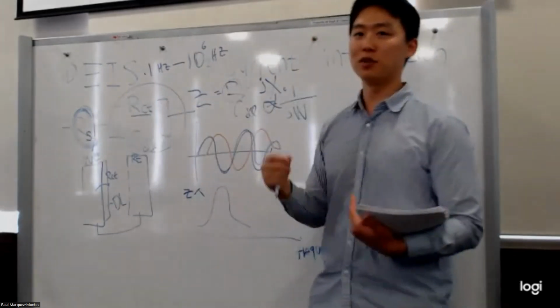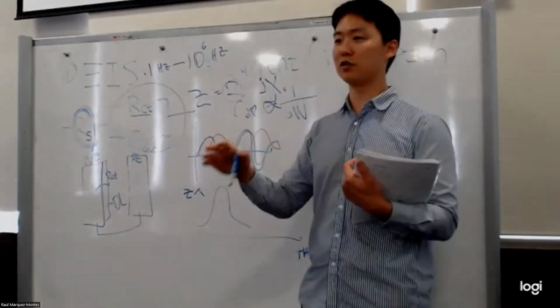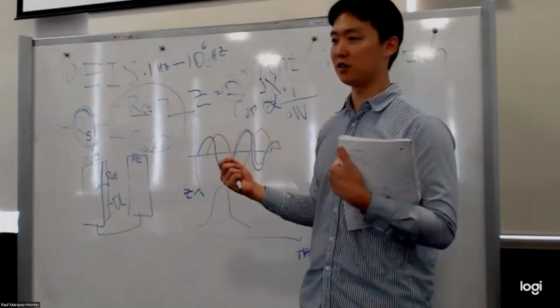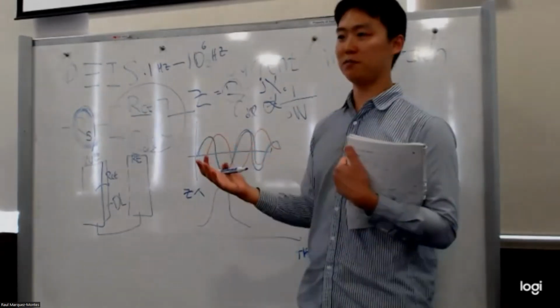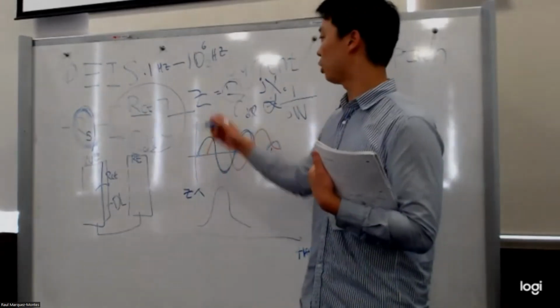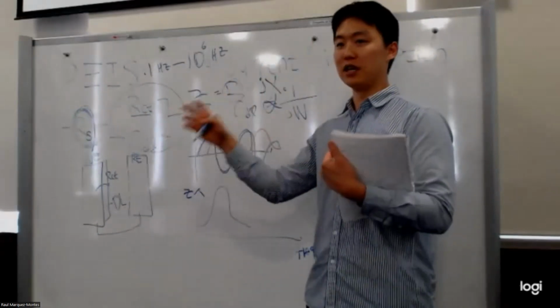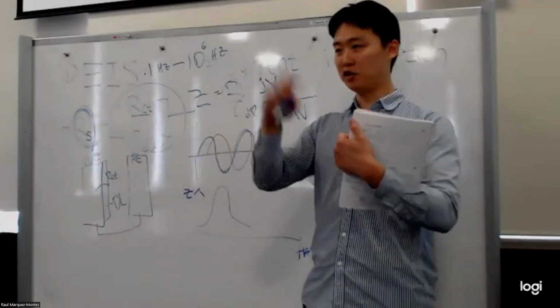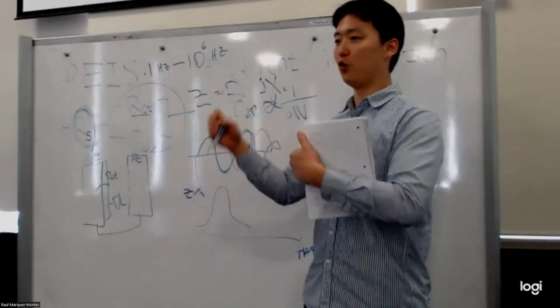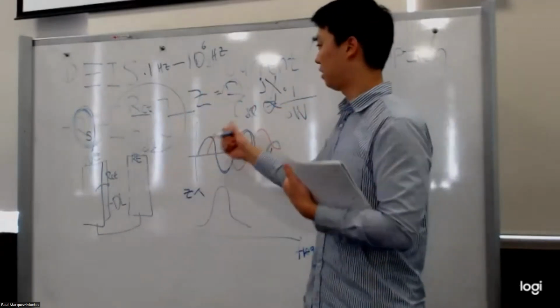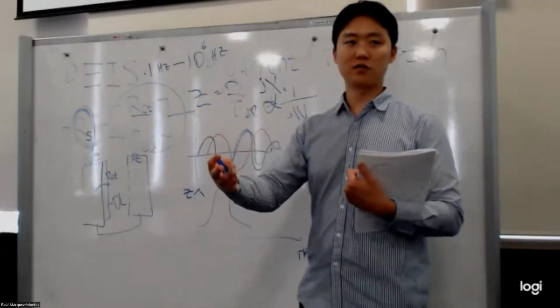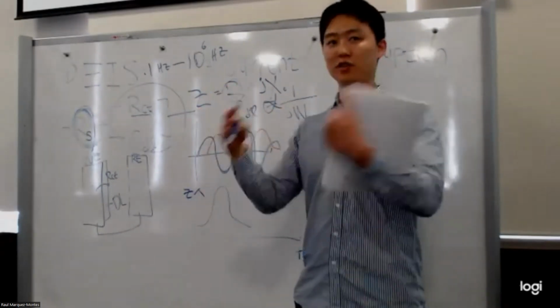So impedance is really powerful in that we can decouple the frequency-dependent impedance signals in the electrochemical system. Even though we have more RC circuits, which means more electrochemical processes, if they have different kinetics for each process, we can decouple and obtain the charge transfer resistance or their double layer capacitance separately.